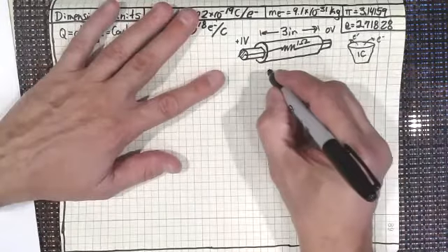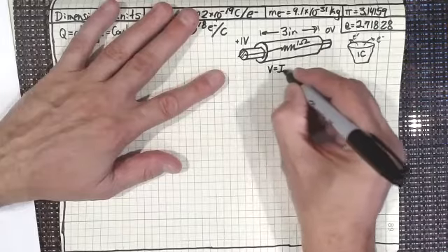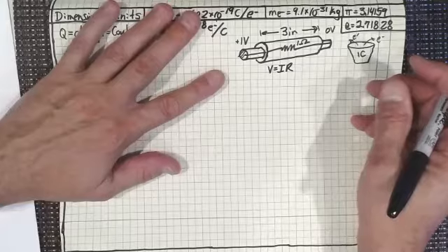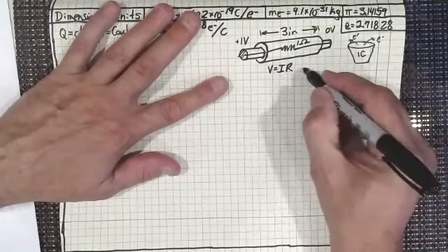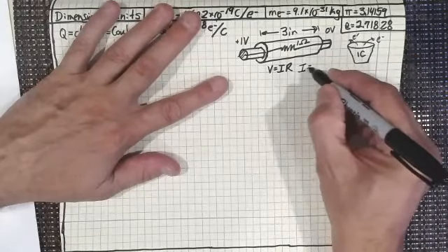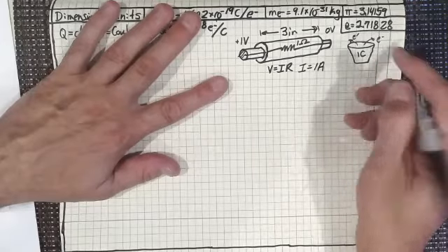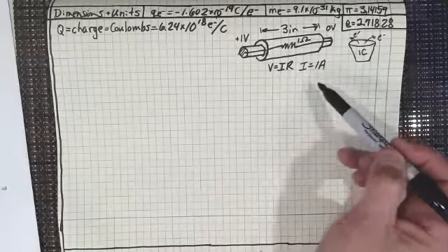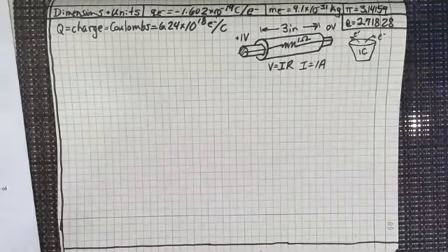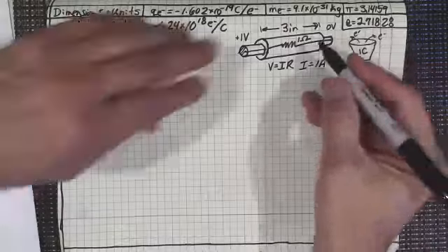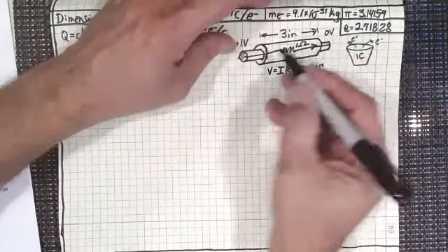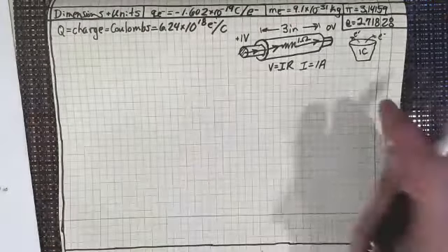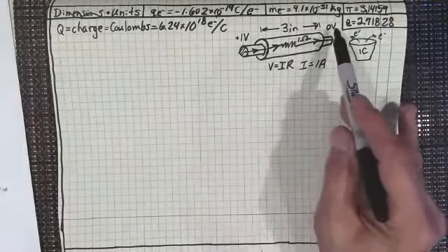And we've got it. Now, with Ohm's law, V equals IR, and some of you may be familiar with that from high school. From Ohm's law, that tells us that the current flowing through that wire would be 1 amp, right? Because I would have voltage, 1 volt, divided by R, which is 1 ohm. That would give us 1 amp. So I would have current flowing through that wire. And of course, we know that current flows from the positive to the negative, right? So I'd have current flowing through that wire from the positive to the negative.